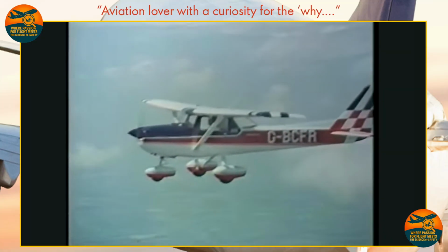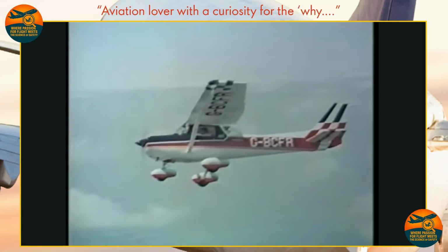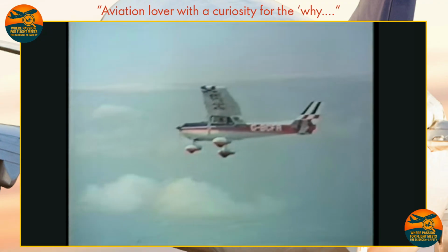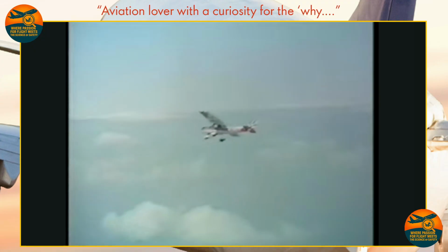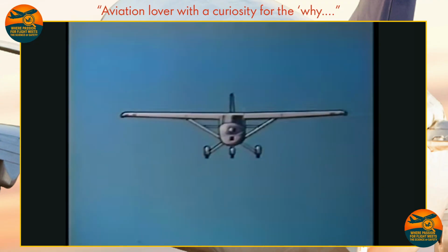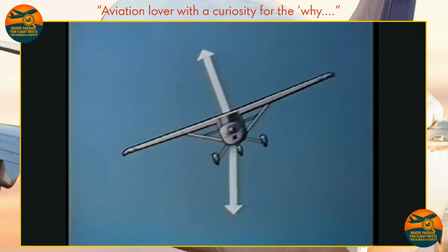Here it is lift that provides the principal turning force. We've only to bank the aeroplane slightly in the desired direction, and even a small proportion of lift acting towards the center of the turn is powerful enough to pull the aeroplane in that direction. This means that lift has a double role to play in the turn. As we bank into the turn, lift acts partly into the center of the turn to counter centrifugal force and partly vertically upwards to balance weight. The aeroplane turns.